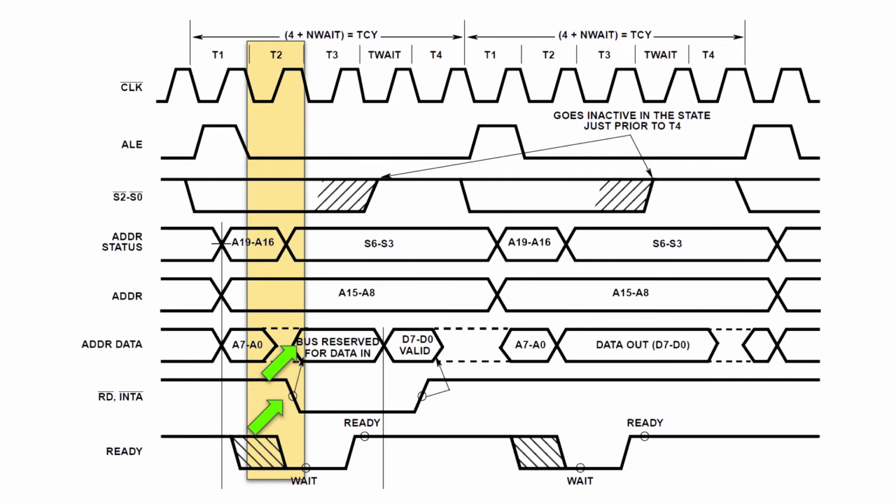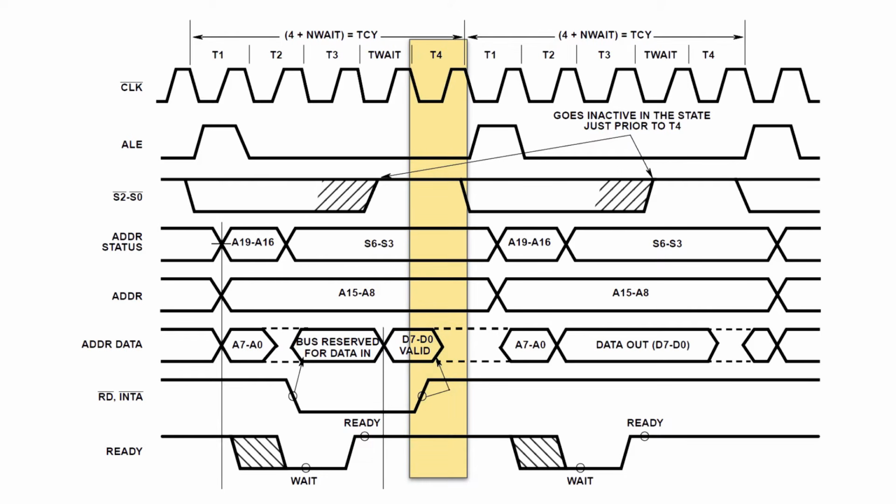One of the RD or WR becomes active, again, depending on whether the CPU wants to read or write the data. Then, in the third cycle, the CPU gives the memory or the I/O device time to get ready to be read from or written to for another cycle. The last, 4th clock cycle makes all the control signals and the address data lines inactive. Then the whole process can repeat if the CPU requires to transfer more data.